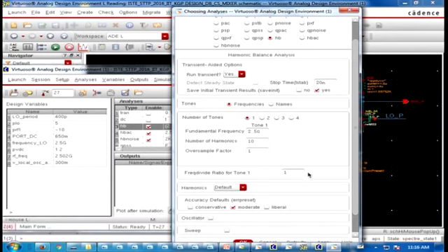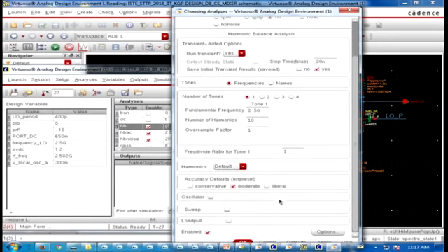Secondly is the frequency divider. Oversampling 1. No, it is suggested 1. ADS might differ, but in Cadence it is suggested 1. You can go through the Cadence support online and declare it there, and they will suggest 1. So the frequency divide ratio is 1 because I have not used any kind of frequency divider. And then I don't have to go for very high accuracy for the transient analysis, so moderate is sufficient. And okay, that's all.